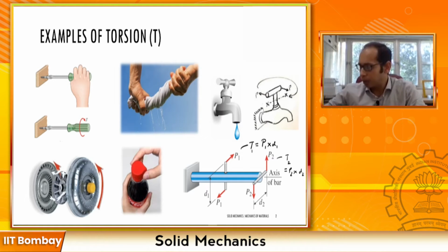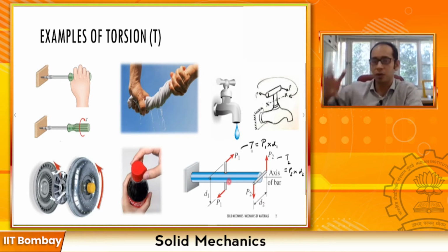And if you appreciate the differences we discussed earlier compared to the bending moment, right? Now the torque acts essentially along the axis of the member. So here if you take P1 and P2 and if you curl your fingers, your thumb points towards the axis of the member, either inside or outside. For example, for the P2, if you go from this P2 to this P2 over here by curling your fingers, again, your thumb points outwards from this particular axis that is there, right?